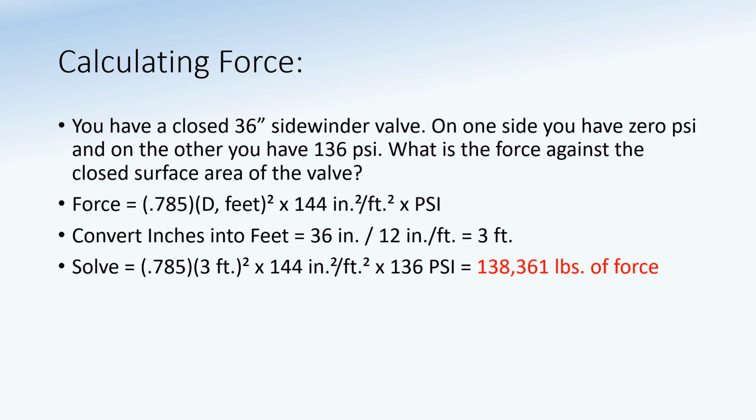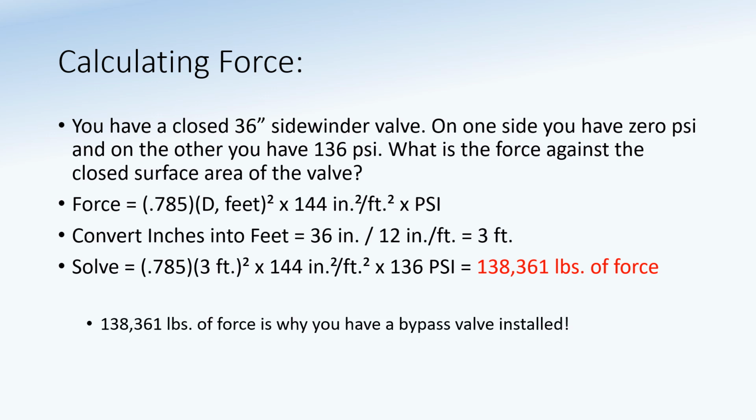So, do you think it will be easy to open this valve if you were in this situation? Not likely. All right. And again, this is why you have a bypass valve installed on a Sidewinder, just to help equalize forces or pressures on both sides of that valve to make the operation of that valve easier.